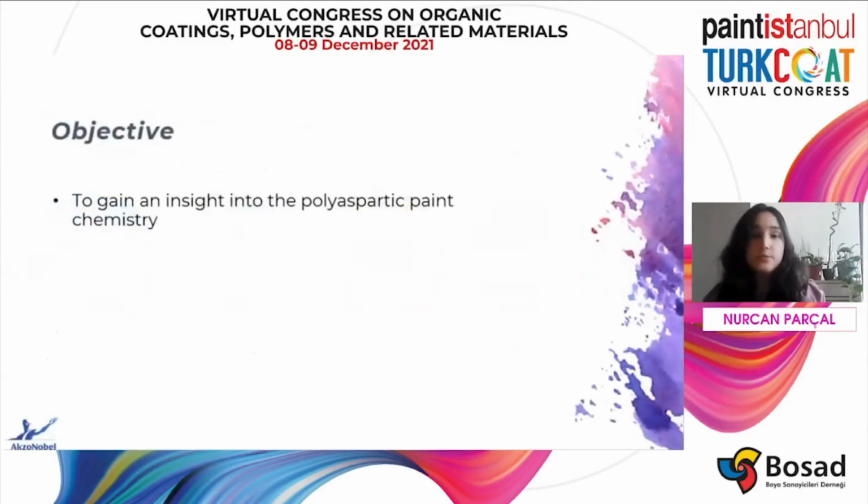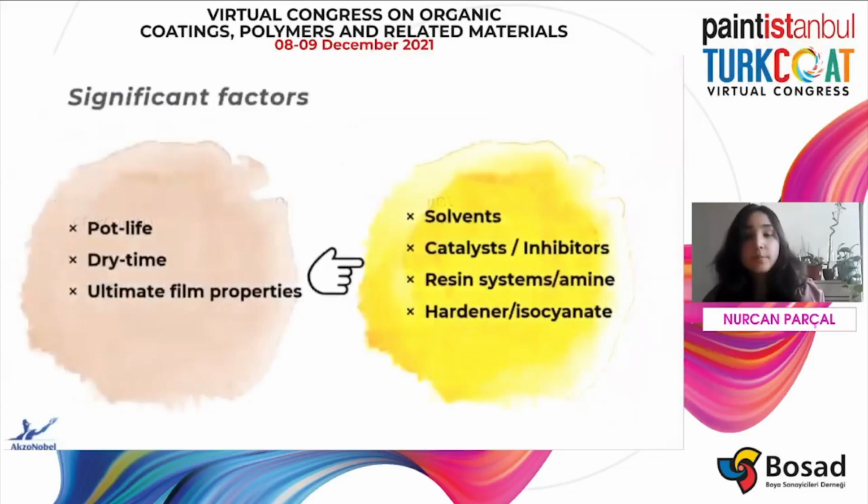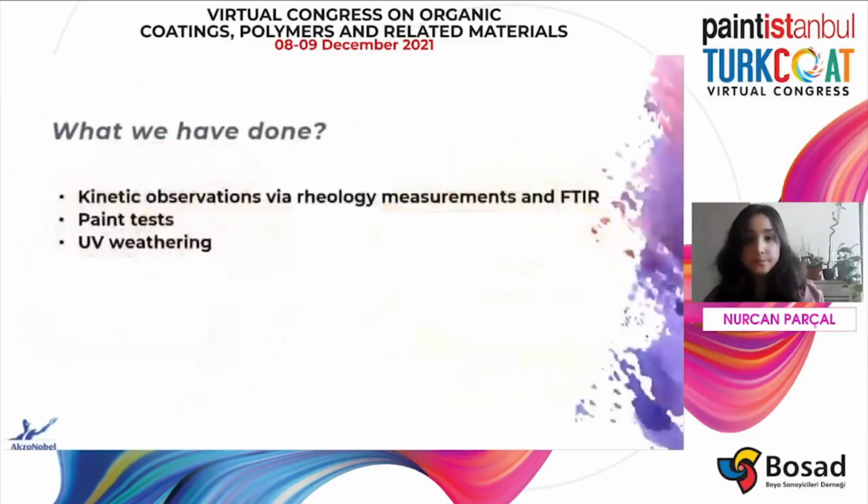So our objective was gaining an insight into the polyaspartic paint chemistry by investigating how pot life, dry time, and film properties change with solvents, catalysts, resins, and hardeners. For this purpose, we did kinetic observations via rheology measurements and FTIR, also paint test and UV weathering.